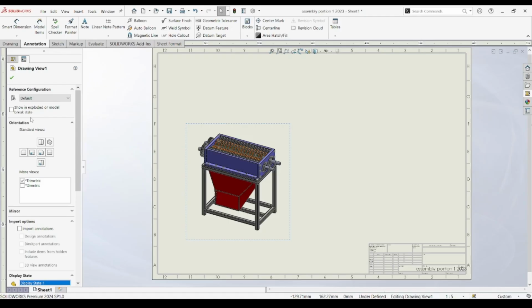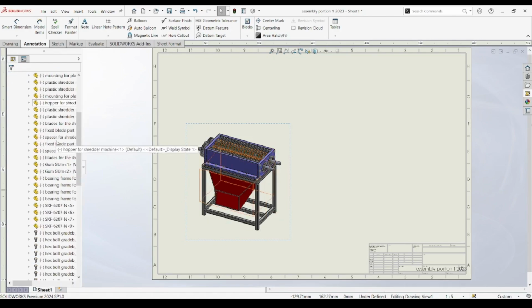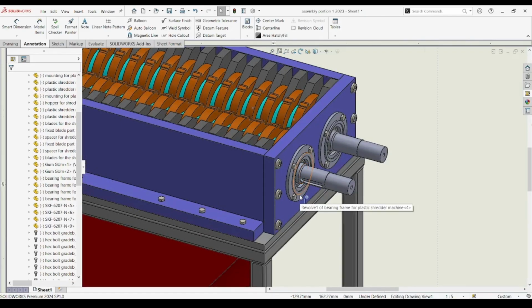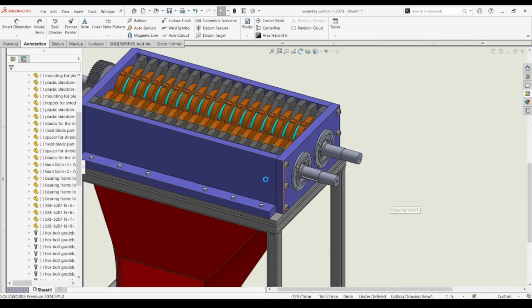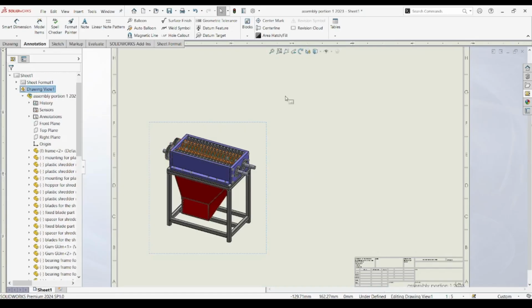We also walk through how to link each column to properties inside the part files. If you've set up custom properties within your parts, such as material type, thickness, finish, or manufacturing process, these will auto-populate into the BOM. If you haven't done this yet, no worries. This video shows you how to quickly add them retroactively.